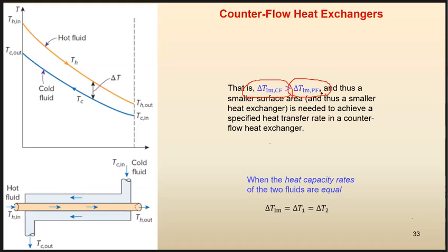And typically in industry, in any application, although the arrangement and the geometry of the heat exchangers are going to be more complicated, especially for compact heat exchangers, they try to arrange the flow streams in the cold side and hot side such that it's similar to some form of counterflow heat exchanger rather than parallel flow heat exchangers.